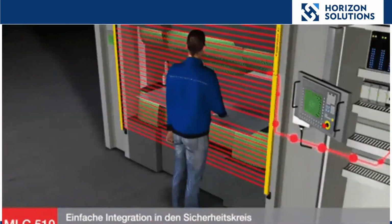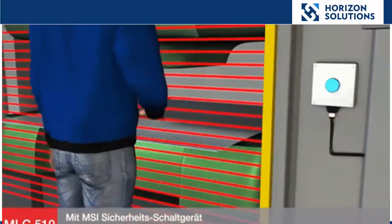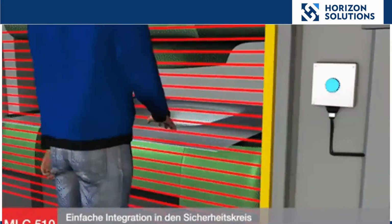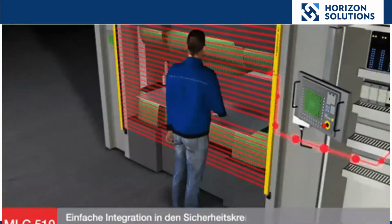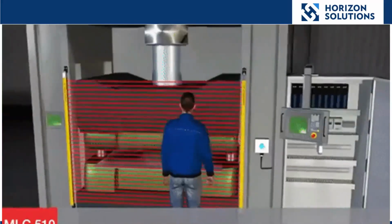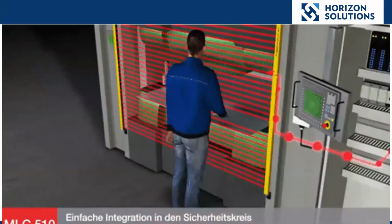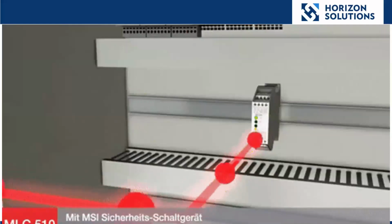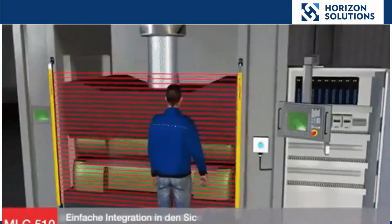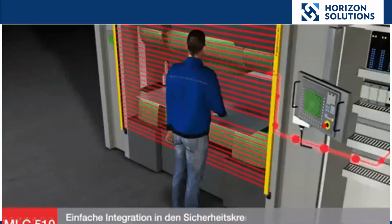However, oftentimes safety presence sensing devices are mounted where it's convenient, such as on the front of rigid guarding, or on strut work, or on pre-existing fencing, without calculations done to determine if the hazard will actually be stopped in time, or if footprint space could be saved on that machine design by doing the calculations and bringing those safety input devices in closer to the machine in certain cases.